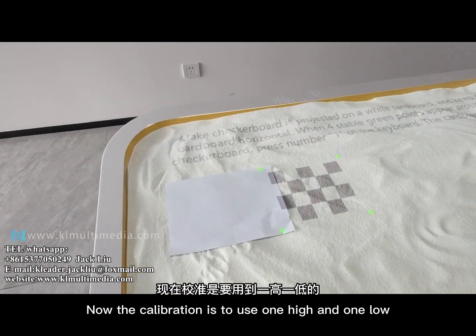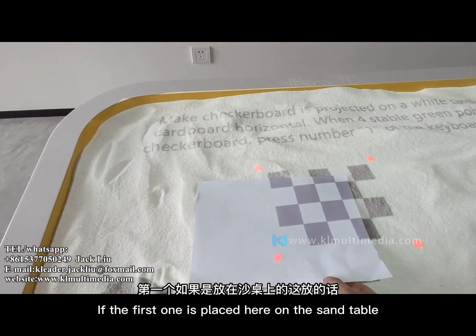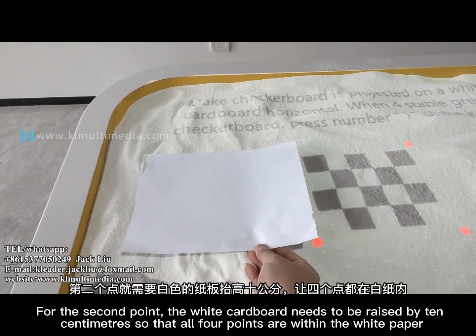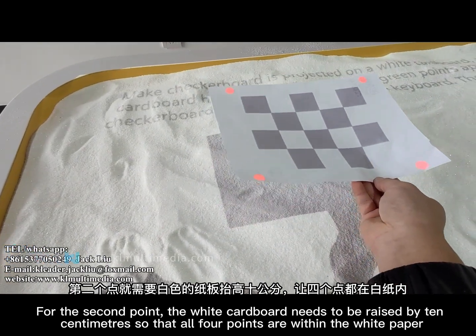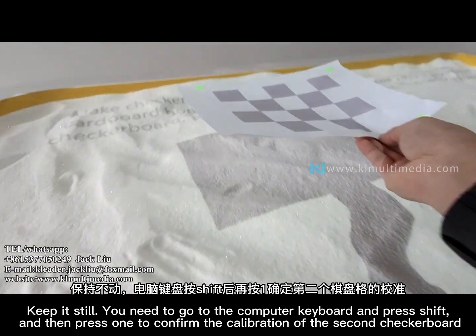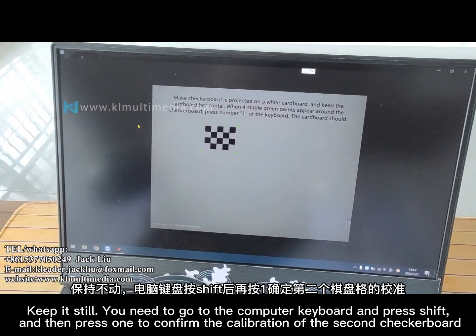Now the calibration is to use one high and one low, such a calibration pattern. If the first one is placed here on the sand table, for the second point, the white cardboard needs to be raised by 10 centimeters so that all 4 points are within the white paper. Keep it still. You need to go to the computer keyboard and press Shift, and then press 1 to confirm the calibration of the second checkerboard.